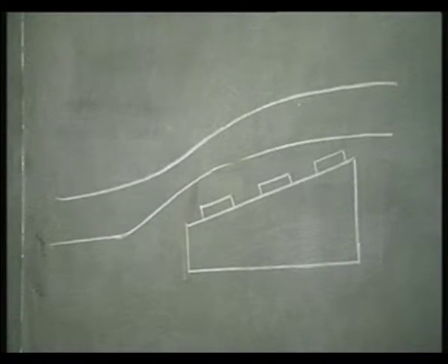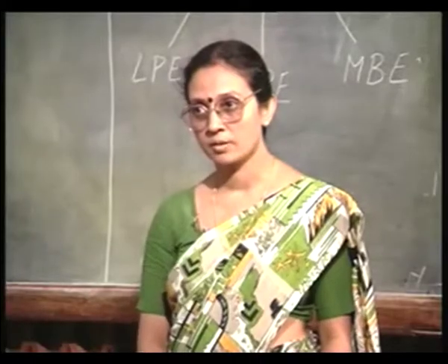The top surface is an inclined plane and the samples are kept like this. So, that as you go down the length of the tube, the samples are placed higher. So, that the effective width of the stagnant layer remains more or less the same, so as to ensure equal growth rate for all the samples.